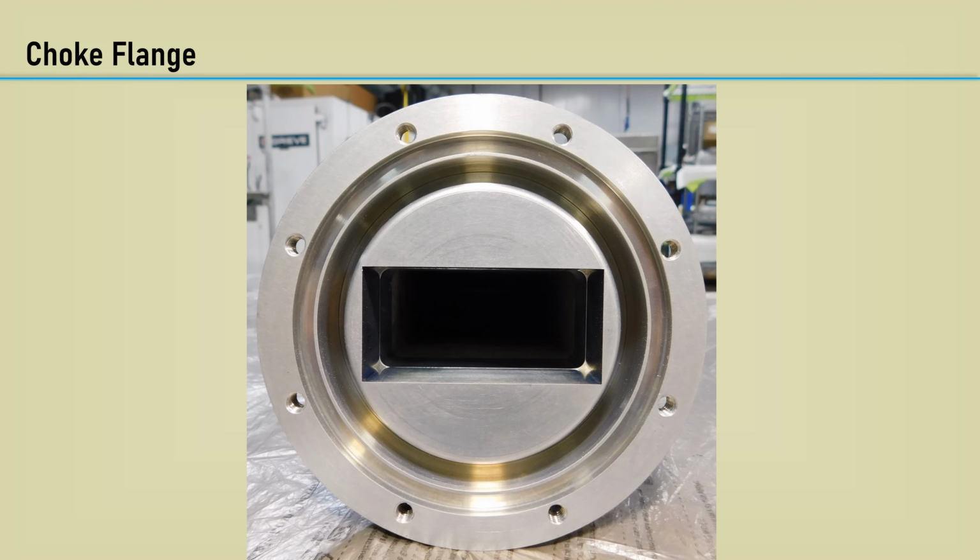Notice the vertical stub varies in length across the circular geometry with relation to the broad wall. This results in a small VSWR that will increase, if not quarter wave. Some flanges have rectangular vertical stub features instead of circular to mitigate this effect.